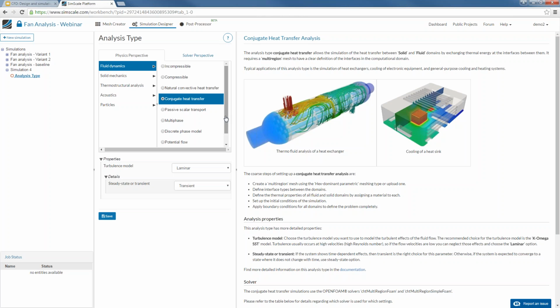conjugate heat transfer, in which not only do you see the buoyancy effects created in the fluid domain, but at the same time you simulate the heat transfer within the solid domain. You can have a full simulation of a heat exchanger with 2 or 3 fluids separated by a pipe of a certain thickness, all modeled at once with the proper behavior of the thermal analysis at hand.